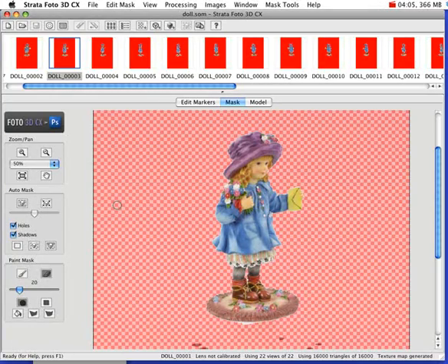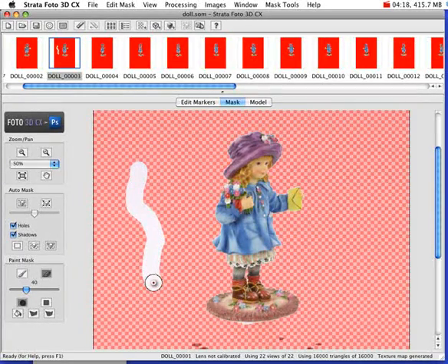So for example, I have selected the round brush, and the diameter of the brush is 20. Move that up a little, and if I click and drag in the window, you can see that I am unpainting the mask or removing the mask. There are times when you'll need to do that on the object itself. So let me go ahead and undo that.